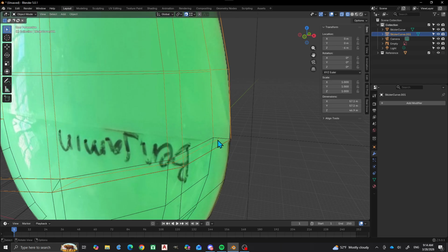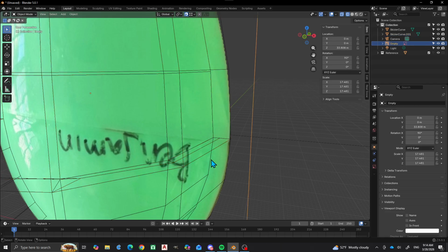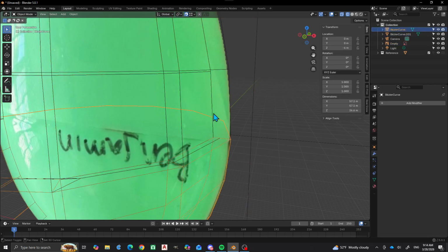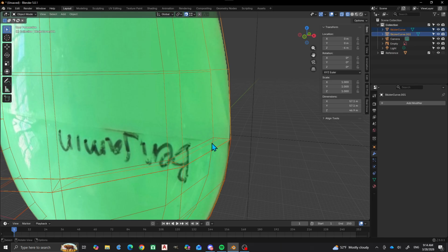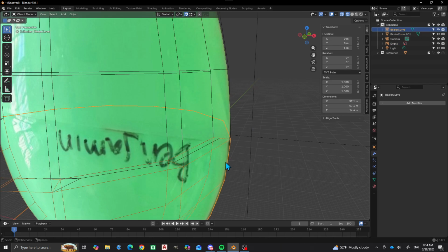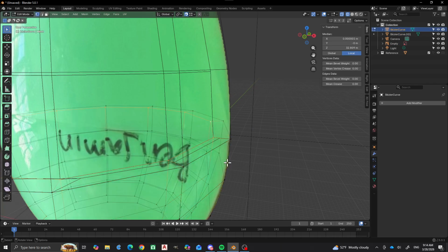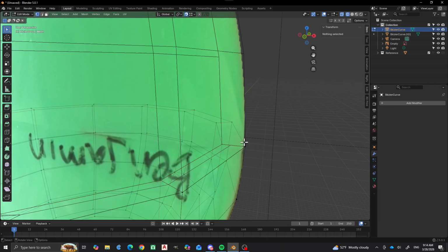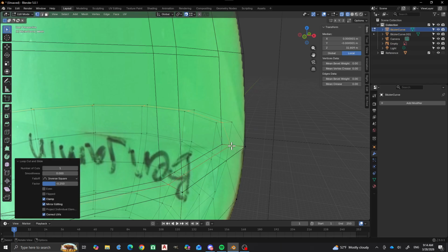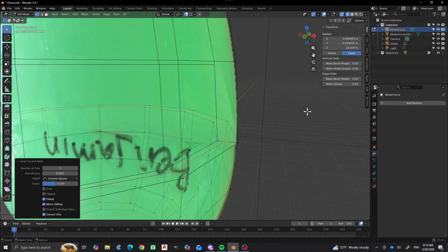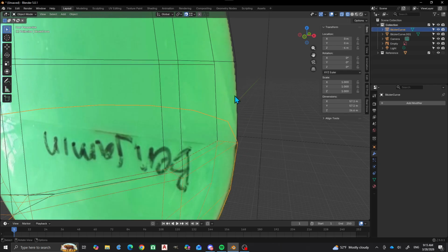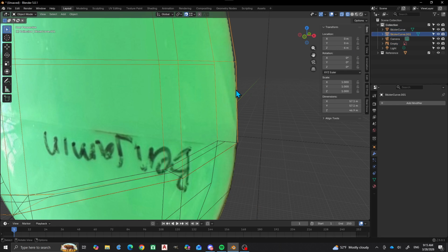And it looks like what I did was I cut, okay, because I did 2 selections here, right? I got both of these, and I ended up making this cut here on this top eggshell. I wanted that on the bottom eggshell, but you know what? That's fine. Because you know what? I can do this. Shift R or Control R. Okay. All right, so there we go.